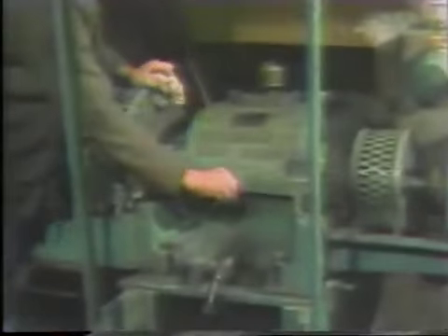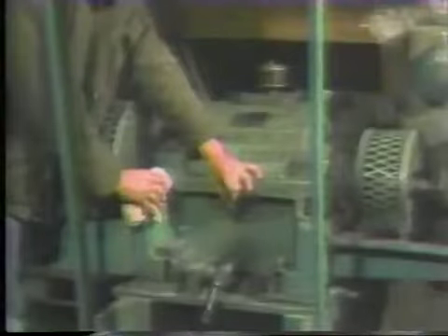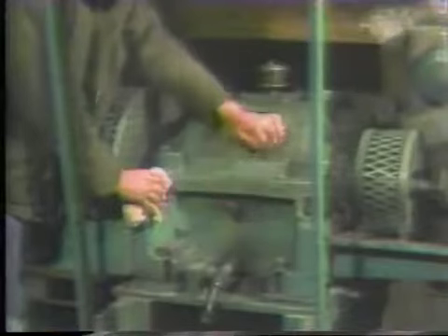On some bearings, there may not be a sight glass or a dipstick. In this case, there is usually a spill hole located on the housing where the normal level of oil should be. The operator can remove the spill hole plug and look inside the reservoir to check the level.